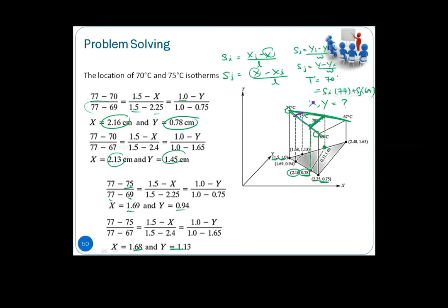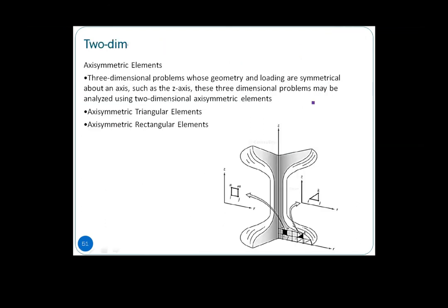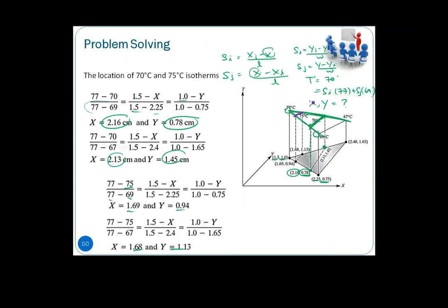Next, we have basically covered all the two-dimensional elements that are available. Later on in analysis you will also see that you can choose these when you are dealing with surface bodies, or 2D analysis. So we have quadrilaterals, linear and quadratic, and triangular, linear and quadratic.